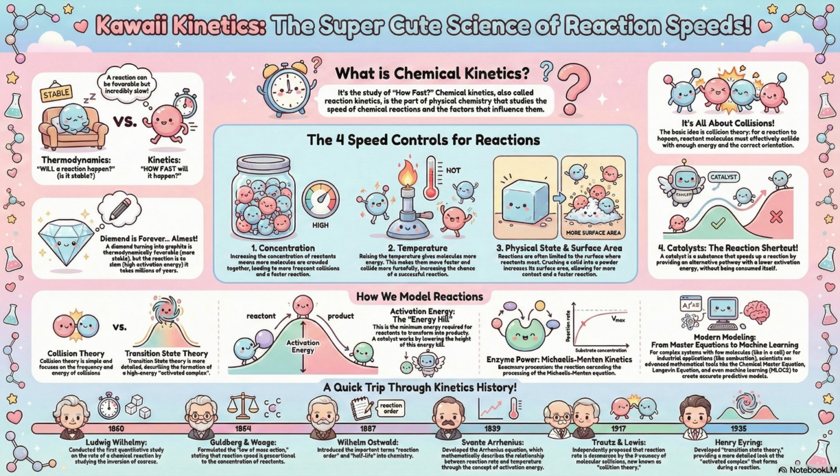Okay, but in the real world, in industry, reactions are almost never single steps. They're complex chains. They are. You get these long chain reactions with highly reactive, very short-lived intermediates. And to analyze those, you need a special tool. The steady state approximation, SSA. Developed by Chapman and Bodenstein way back in 1913. The core assumption of SSA feels a bit weird at first. It assumes the rate of change for the intermediate's concentration is 0, but it exists, right?